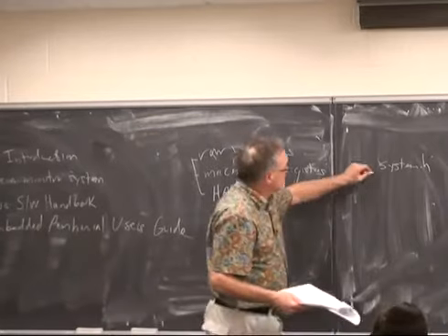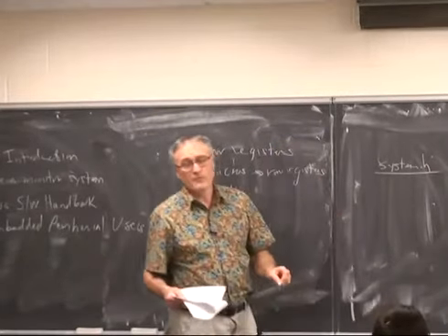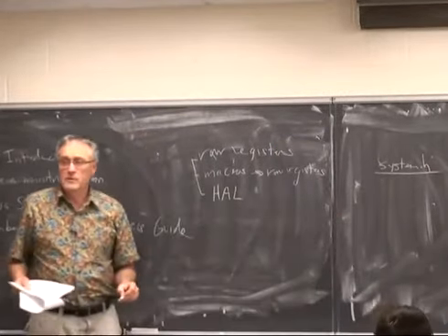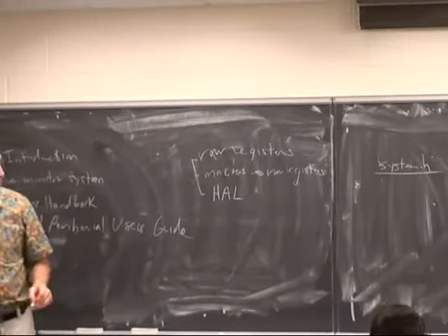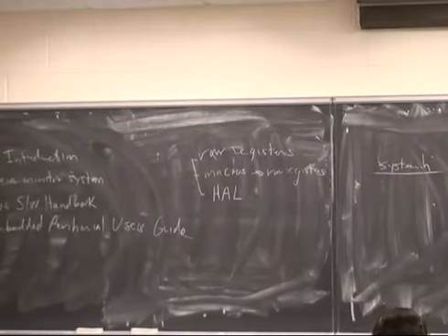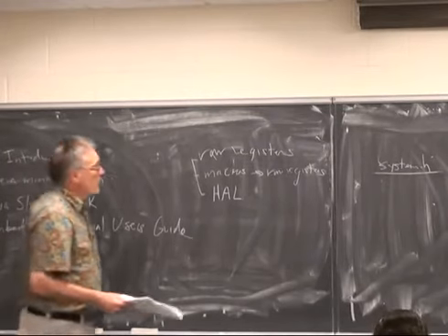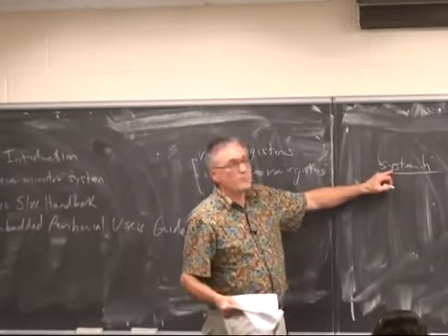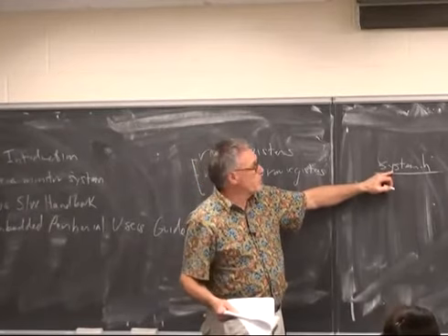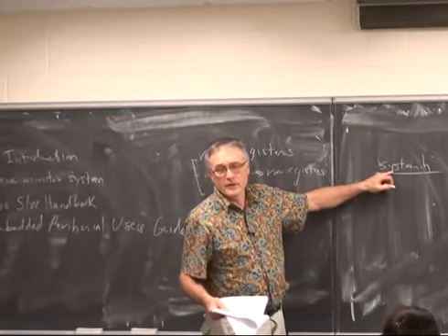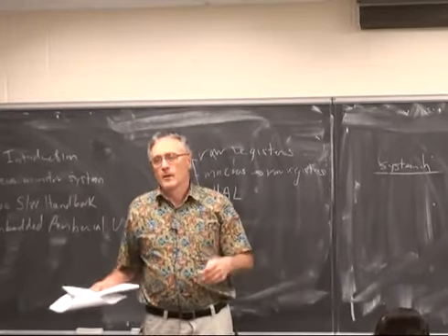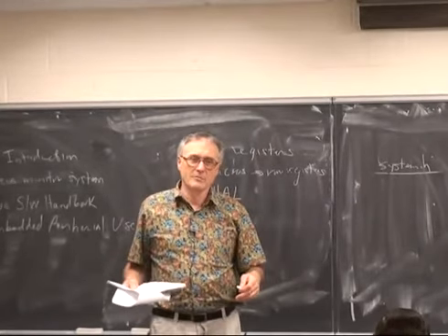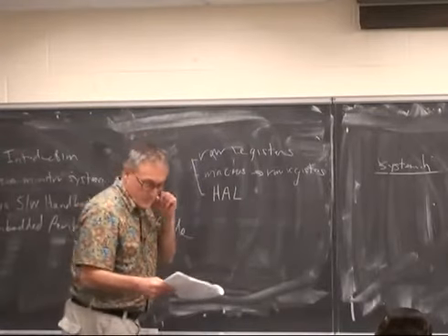The system.h file will be someplace in the folder or a subfolder of the project that you are building, and you can search for it. It's faster than looking for it by hand. So almost every time you build a new system, you're going to want to look at the system.h file to find out various things about where SOPC Builder put your peripherals.